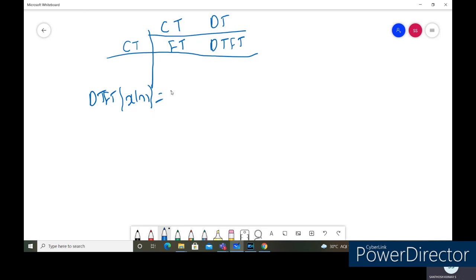That is given by X of e to the power of j omega, and the formula is the summation from n equal to minus infinity to plus infinity of x of n into e to the power of minus j omega n. This can also be written as X of j omega. These are different notations, different ways of representing the signal in the frequency domain.